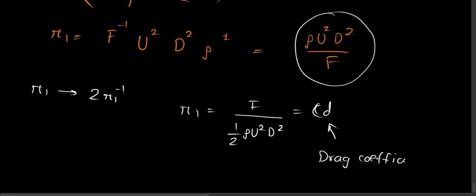This way we derived the drag coefficient, which is widely used in aerodynamics or hydrodynamics to calculate the drag acting on a body, in this case a cylinder or any body with diameter D. You just looked at the process of how we derive the similarity parameters, and now you have a clear understanding of how you can derive other parameters as well. In our next lecture, we'll use the Navier-Stokes equation to derive some other really important parameters, which help us in practical engineering to scale down or scale up our model accordingly.